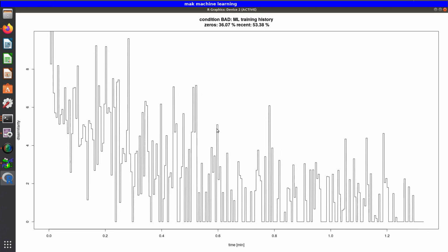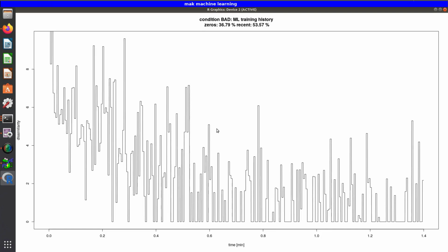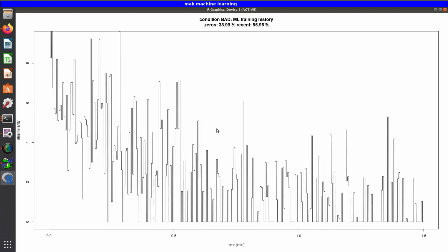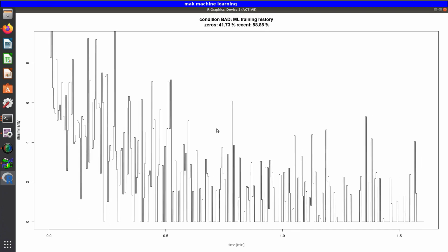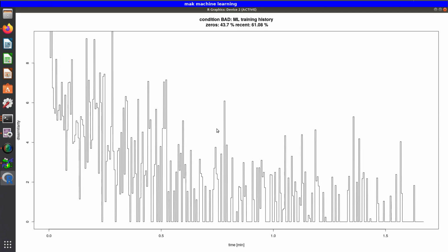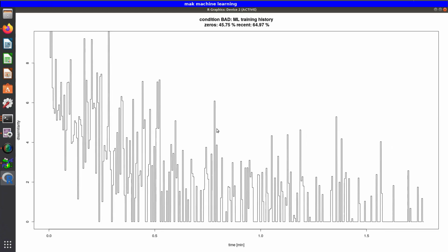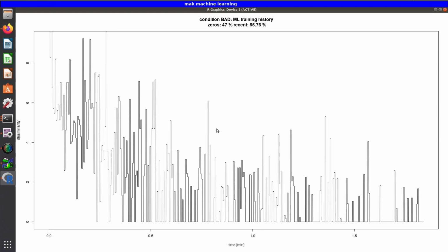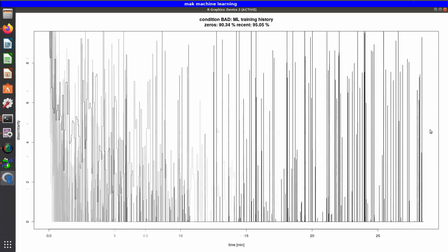Our live training monitor shows us the percentage of zeros over training time so far, and the value for recent is the percentage during the second half of training time. So watch how the percentages displayed at the top are increasing. Since there is a warming up once the bearing is running, and because speed may fluctuate, we have to choose a training time that is sufficient to cover the acceptable variability during a specific condition. We have chosen a training time of 30 minutes.